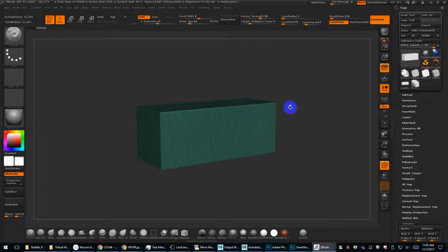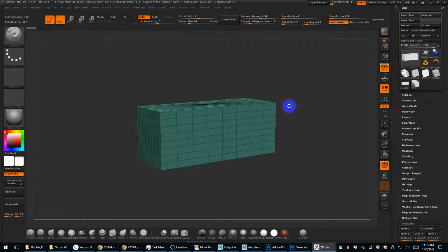Now Dynamesh, this gives me 30,000 polys. So remember, if this brick is going to be in your scene dozens to potentially hundreds of times, you do want to try to keep it light and manageable, so you can do stuff like trim off the end bricks, like I just had an issue with. Those bricks were really heavy.